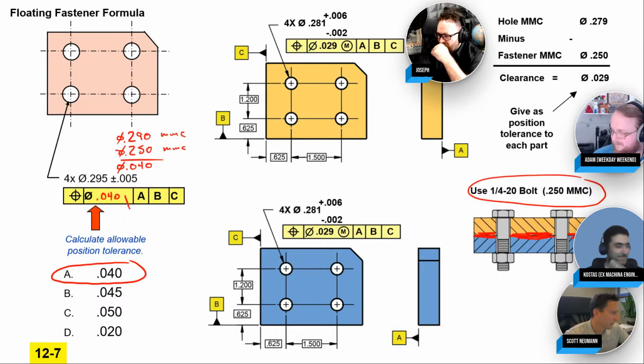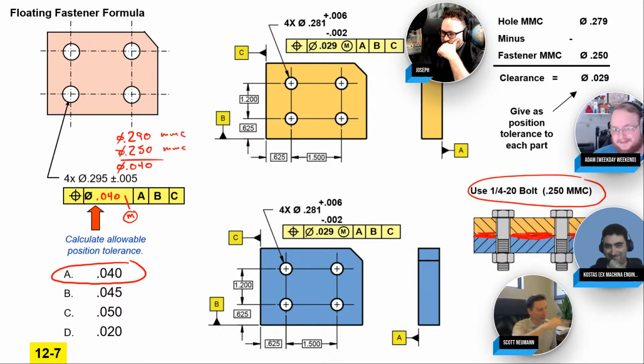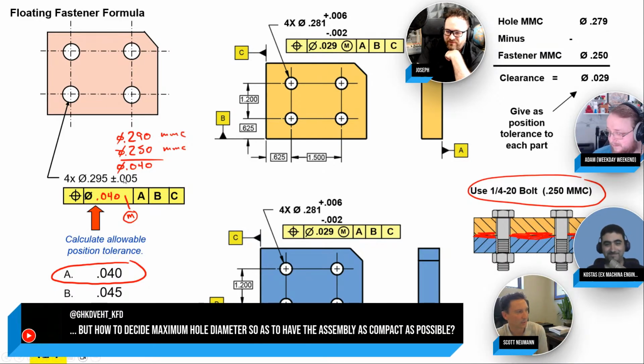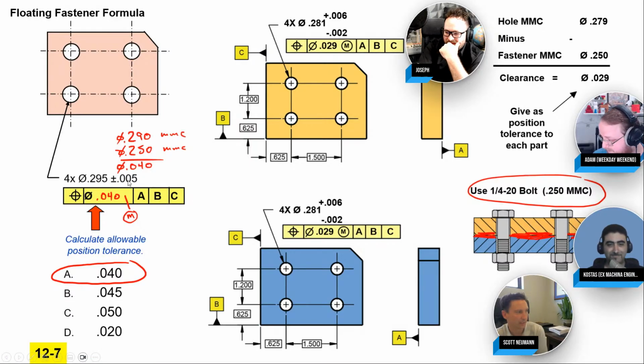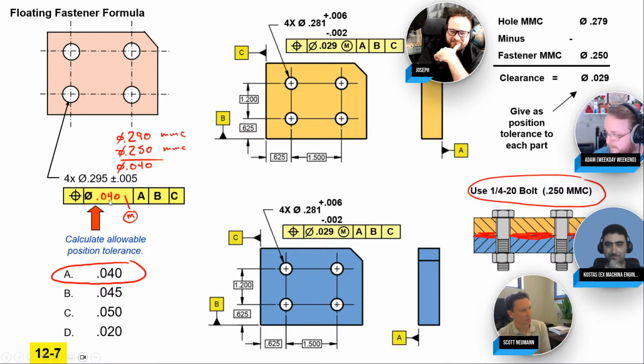Now, sorry, but having worked on both sides, machinist and designer, machinists care about the tolerance as well because that's where the cost is, right? True. Yeah, they're definitely looking at that range. They're looking at the distance between your goalposts, and they're like, all right, I need to kick a field goal out here. How big is this field goal? What is the width on my zone? Good analogy. Here's that range between the goalpost, from a 290 to a 300. That's what they got to put that size of a hole in there. And then they also have another spec, make sure you're accurate. And this is pretty loose tolerance here, 40 thou, but maybe for a shim or something that might be necessary.